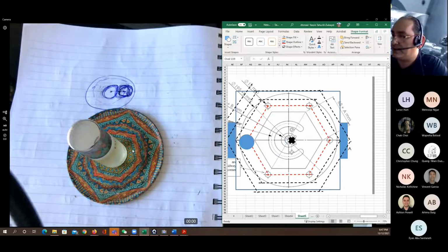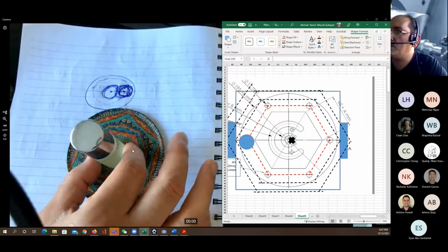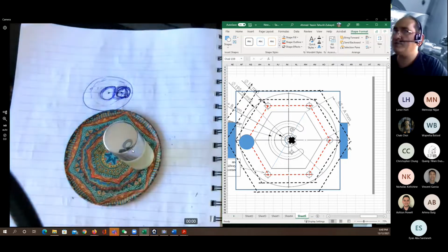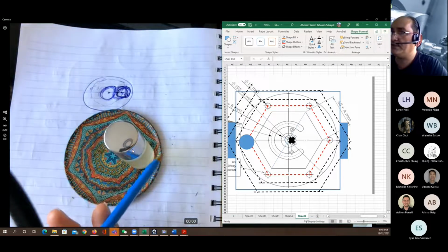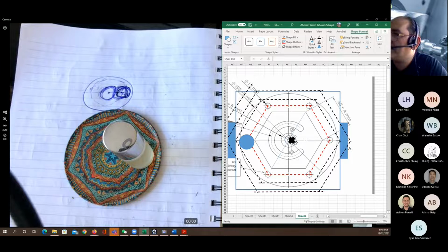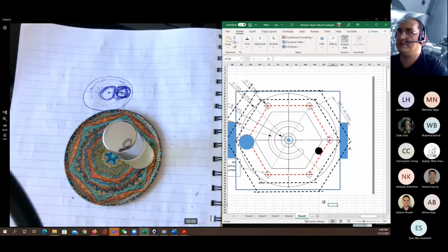And now we are close to it. Then we go to the G01 to the side. Now, just to be sure that the side of the cutting tool here is going to be attached to the circumference of the work part. That means the circle, which is denoted as a blue circle in this diagram, this circle should be offset from the black circle to the inside by 5 millimeters.